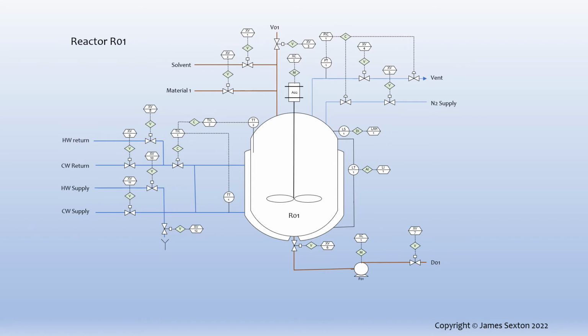The basic control of the valve will typically allow the valve to be controlled automatically or manually. It will take the request to open or close the valve and put the valve in its requested state. It may indicate a fault if the requested action is not successfully achieved. For a level transmitter, the basic control of this device will take a signal and convert it into a form that can be displayed in engineering units.